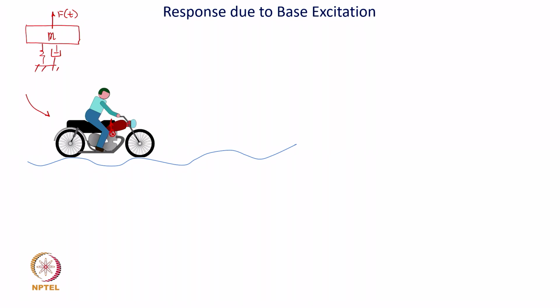So, it is like a mass sitting on some suspension, on the spring dashpot system, and then if we quantify and characterize this inertia property, the stiffness property of the suspension, the damping property, and we know at what speed the crankshaft is rotating and what is the unbalance or residual unbalance in the crankshaft, primary and secondary and so on, we basically characterize the excitation force also. Now, if that happens, then what is the ensuing vibration response which is felt by the rider? That is what we have done in the past. All the time this was modeled like a simplified single degree of freedom vibratory system.